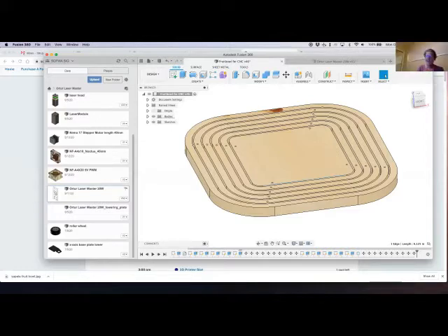Exactly. And some people are doing this kind of inlay in flooring. I think they're maybe using something like the Shaper Origin. And they like a much smaller angle, like the 15 degrees, because after a few years, you may be sanding that floor down again and refinishing it. And you don't want your lines getting wider or thinner by much as you sand the wood down.